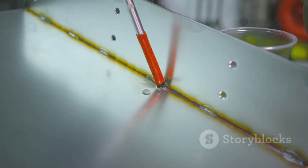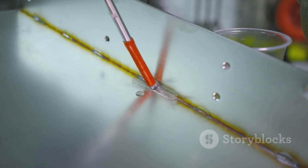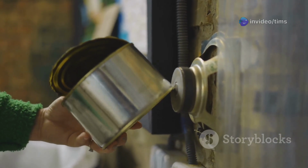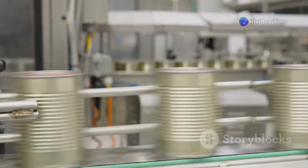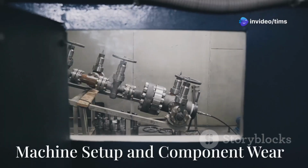Droop is a type of double seam defect that appears as a sharp downward slope or dip in the seam. This dip happens when the seaming machine doesn't properly compress the metal layers. Instead of a smooth, even seam, you get a noticeable dip. This usually happens at the overlap where the two ends of the can's lid meet. This defect weakens the integrity of the seal. A weak seal can allow air and contaminants to enter the can. This is a serious food safety concern.